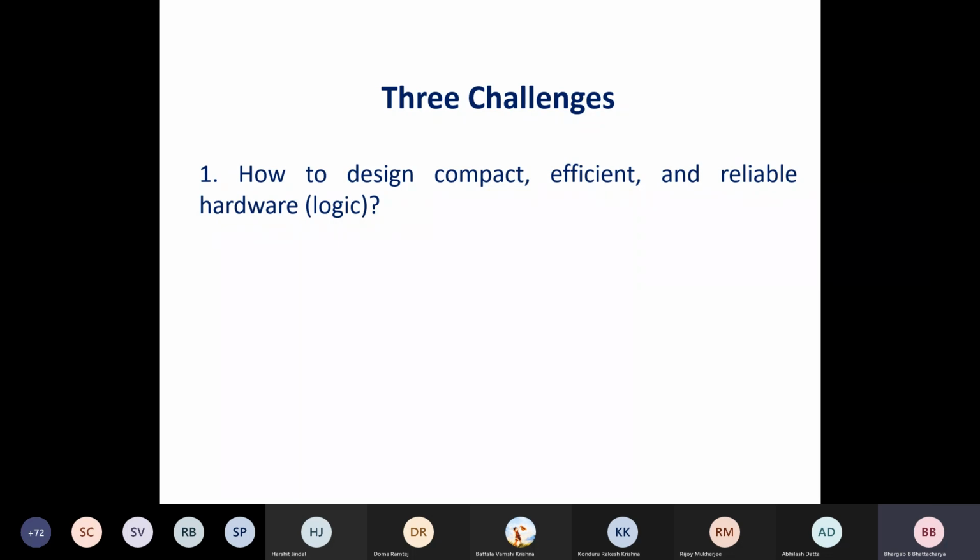A lot of power consumption, yes, because as soon as you want to change the levels from 0 to 1 and 1 to 0, there are some inherent capacitances, because these are physical devices. Those capacitances will be charged and discharged, and in the process, it would dissipate energy.